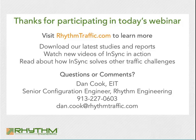Okay. How does InSync handle Black Friday traffic with it being shopping traffic at an odd time? Well, there's a couple things that can happen. For one, like in West Des Moines, Iowa, where we just talked about, the configuration that runs there was able to absorb all the traffic from the mall and all the big box retailers. However, in certain areas, it may be necessary to set up a specific event configuration where you need to offer more time to the side streets, and then the engineer can go in CentralSync and specify at what time the specific event should start and end. So you can have that event end on Black Friday whenever they expect traffic to resume back to normal.